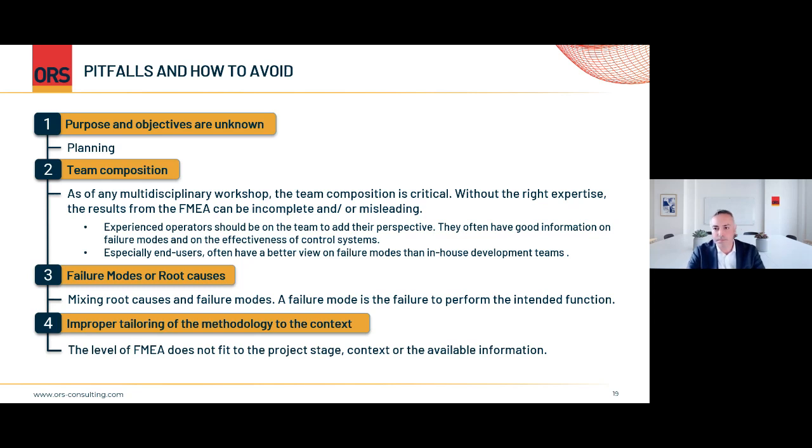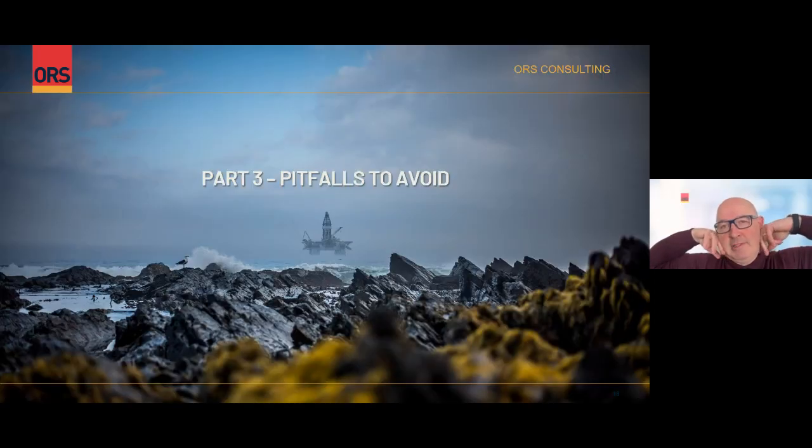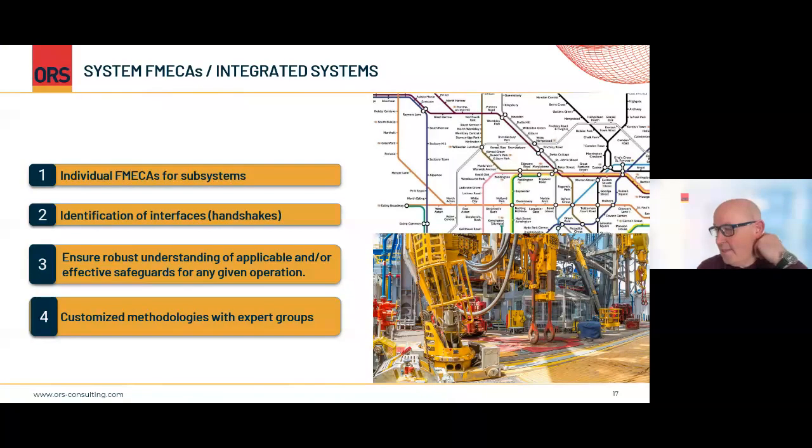Just go back one slide, Baris. Just go back to that before I go on to this. There's a lot of key things Baris mentioned there. You can see that the FMEA or the FMECA can form the basis of such critical decision support. It's helping the team identify what are the important components, which component failures are production critical, which ones are safety critical, what should we do about it.